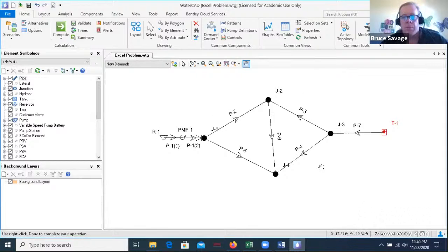Okay. But with that, just as a quick recap, I showed you how to start the program, how to add all the different components with the junctions, the tank, the reservoir, a pump. Make sure you know how to put in a check valve, and then the output of the answer. And from here, you can now go into design. You can set parameters and say, all right, what if the flow or the pressure at one junction is low? Or in a particular pipe, it's kind of low.